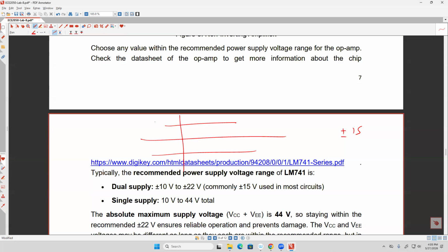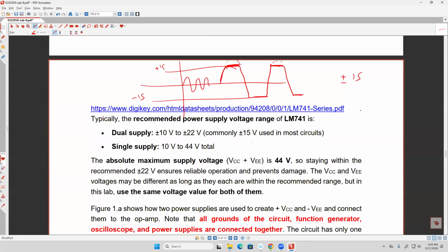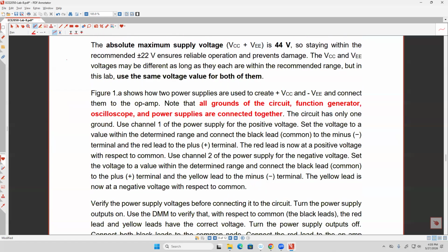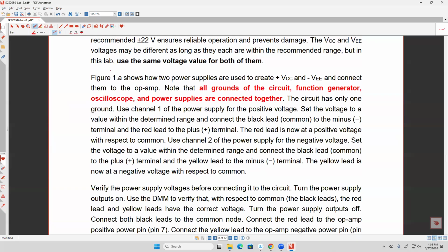As the output here is between positive 15 and negative 15, you will see a very nice sinusoidal. However, if you increase it too much, it's going to be clipped, because simply I can't give you more than that. It wants to go more than that, but I can't. For amplifiers, that's a bad thing. If you want to use amplifiers, we consider something like this distorted. You distorted the signal, so we try to avoid this situation. It's not something good.